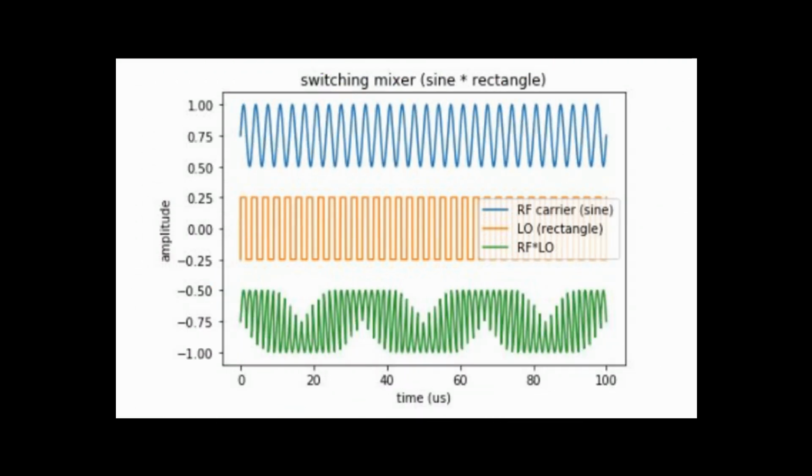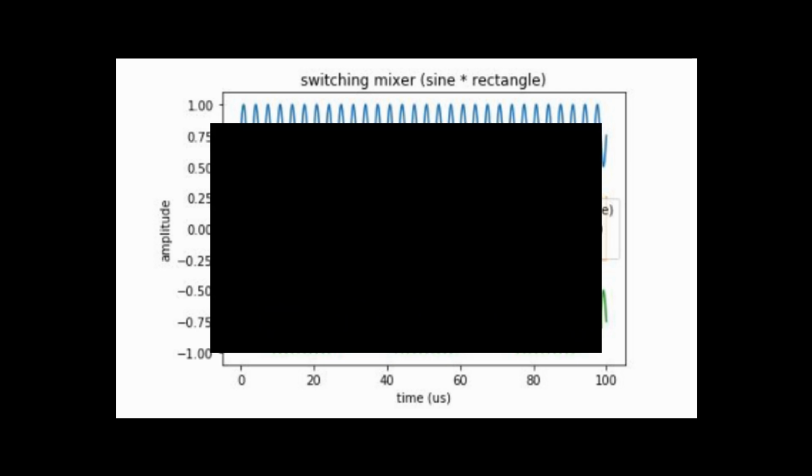here is what happens when two signals are multiplied together. You can kind of see the lower frequency, the F1 minus F2. It's a little harder to see the F1 plus F2, but it's there. This is a fair representation of the multiplication that's occurring in the mixer.